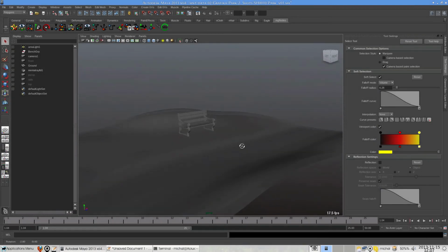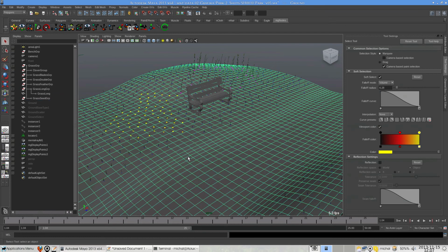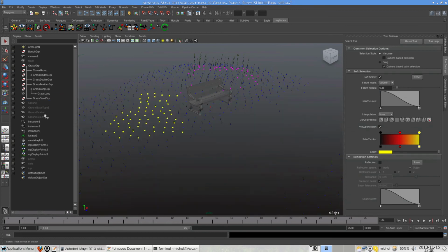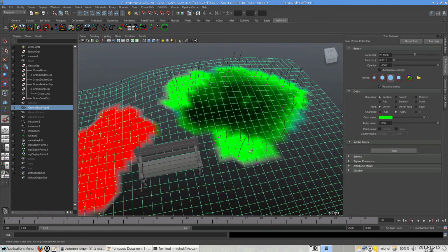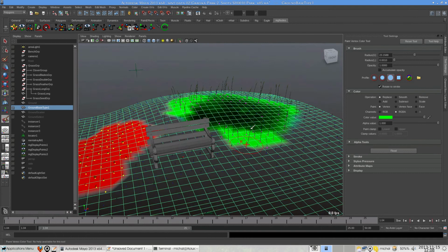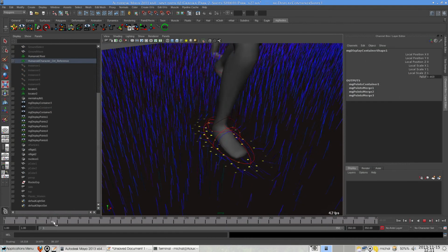In this example, I created park environment, focusing on grass behavior. Using mgNodes, I scattered rocks and different type of grass blades on desired ground parts. Using Maya texture nodes, I defined grass animation. Finally, I set up an emitter to create interaction with rocks.